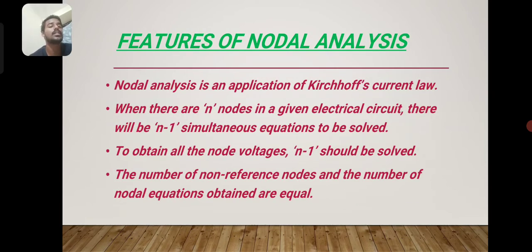Features of nodal analysis. Nodal analysis is an application of Kirchhoff's current law. When there are n nodes in a given electrical circuit, there will be n-1 simultaneous equations to be solved. To obtain all the node voltages, the n-1 equations should be solved. The number of non-reference nodes and the number of nodal equations obtained are equal.